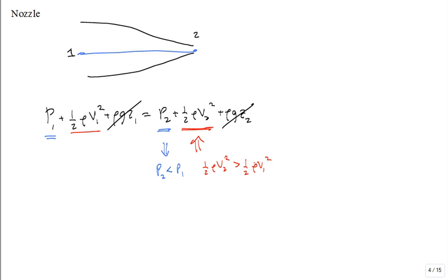Yes. Sure. Now, this equation we've applied is for something like water flow. It's incompressible. Or if you have air, as long as you're not subjecting it to significant pressure and temperature changes, you can often treat air as incompressible as well. I know if you really increase the pressure and change the temperature, it's not incompressible. The density is not constant. It starts to change, but under these conditions you can treat it as if the density doesn't change, quote unquote, it's incompressible, even for air.